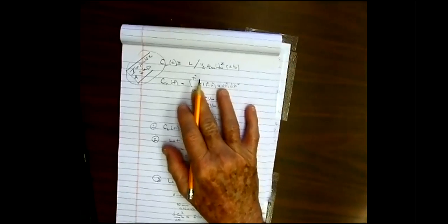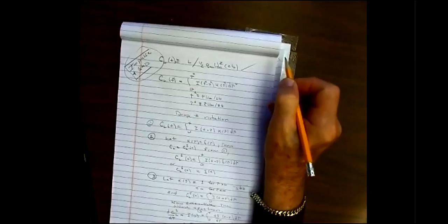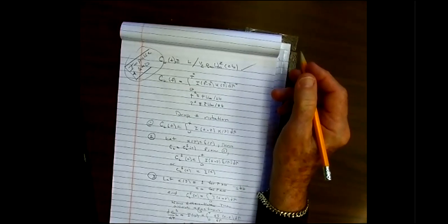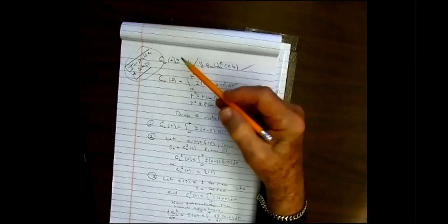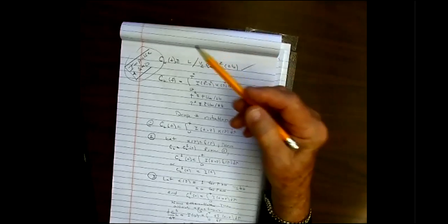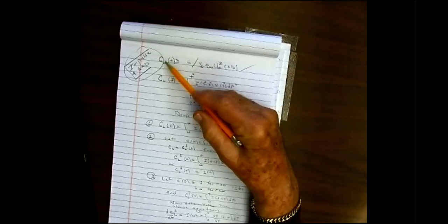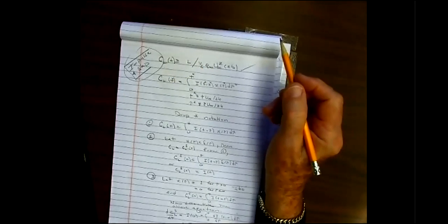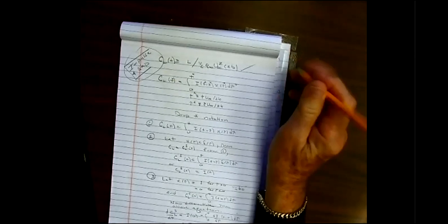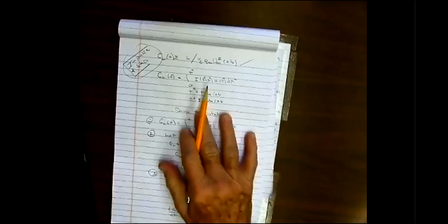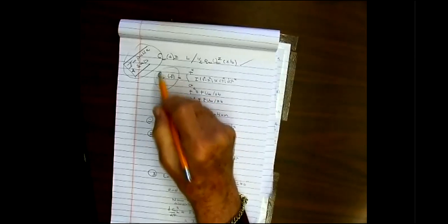So the way we're going to start off is with a non-dimensional. We'll do this in 2 dimensions, but it also works in 3 dimensions. That's even better. But let's think in terms of 2 dimensions at the moment. So here I'm going to non-dimensionalize the lift, and I have a lift coefficient as before. And now the general theory of linear dynamical systems tells me that I can relate the output of the system.